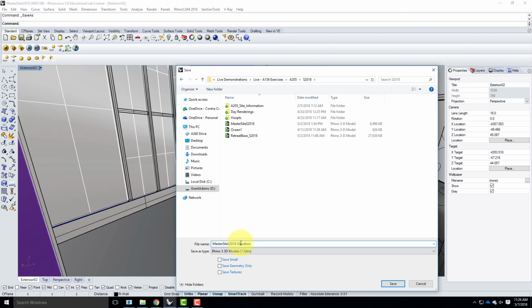And so the other thing about this is that because it's a break, it's a fork in your file, it's not going to go and update with changes later on. So this is a permanent, like, I'm making the elevation now. And you have to commit to, I'm making the elevation now. So if your model's not quite done and you go to do the elevation, it's not going to automatically update later on.